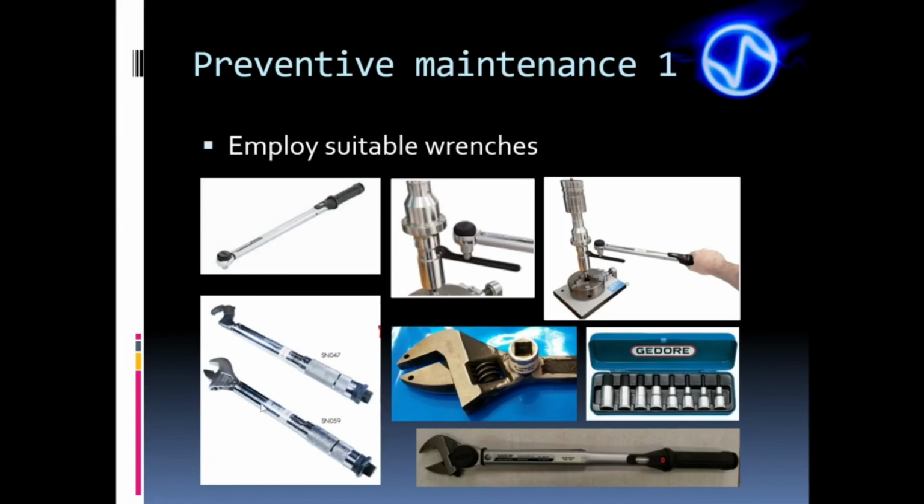In this picture, there are special torque wrenches. These are excellent tools, but in some countries or regions, they may be expensive and hard to find. In this case, an alternative is to adapt a standard wrench by soldering a torque wrench socket to it. After coupling the torque wrench, we have an adapted torque wrench.